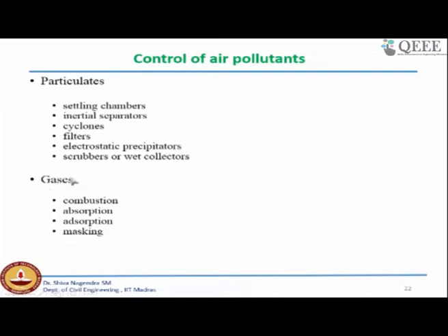For gases, settling is not possible because they are very fine in size, so they will take several days to years to settle down. So for gases we use either incineration, absorption, adsorption, or masking.